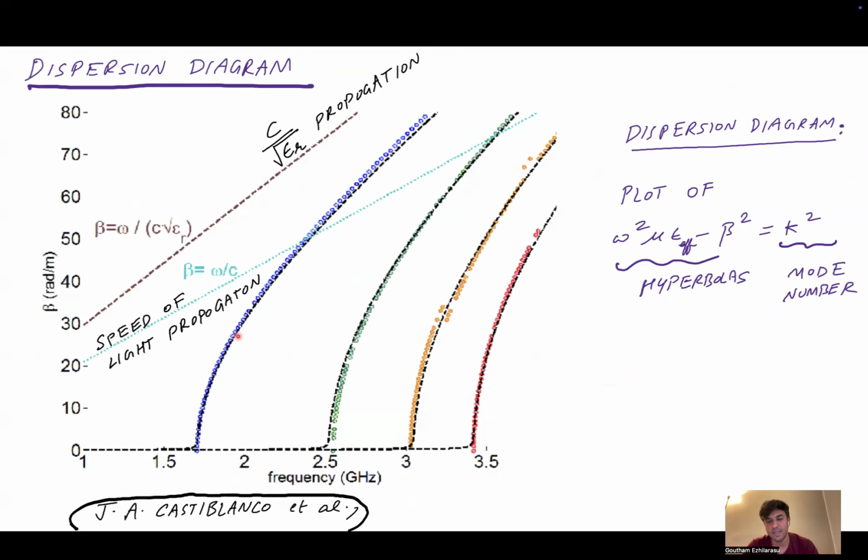This further continues what was discussed in lecture 1 on waveguides: any waveguide has this kind of dispersion relation, which talks about the various possible mode configurations in the waveguide cross section. And each mode pattern in the waveguide cross section can have a different curve depending on the frequency if you plot the dispersion relation. So, for example, each one of these curves represents a single mode, and you can see how the slope of the curve, which is related to the wave velocity, changes with the frequency, right?